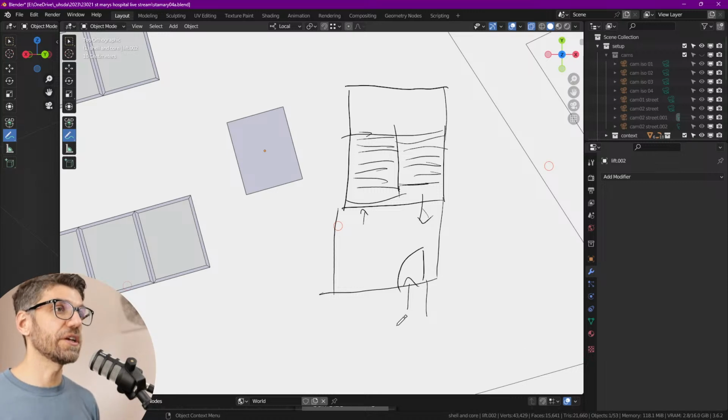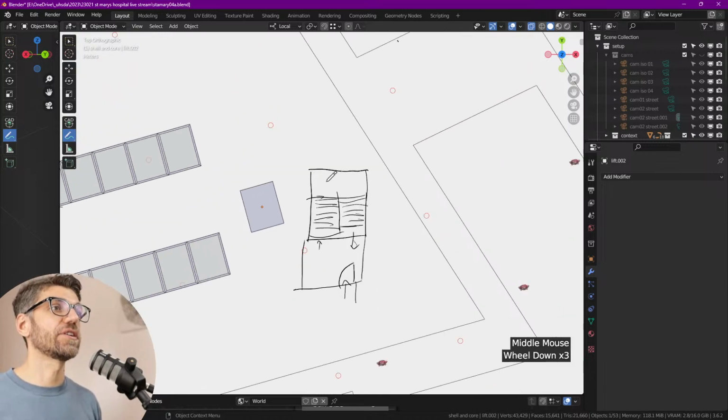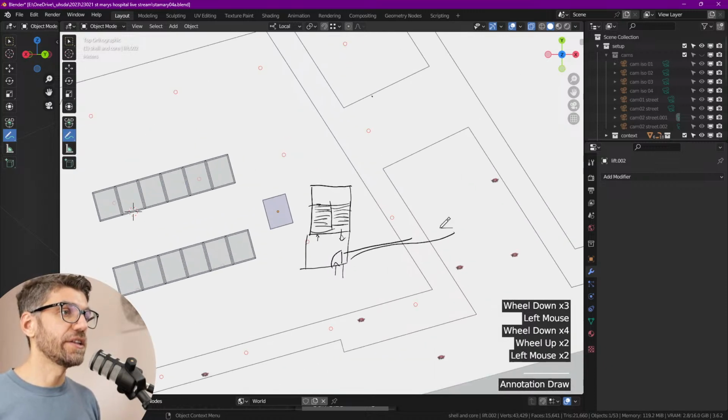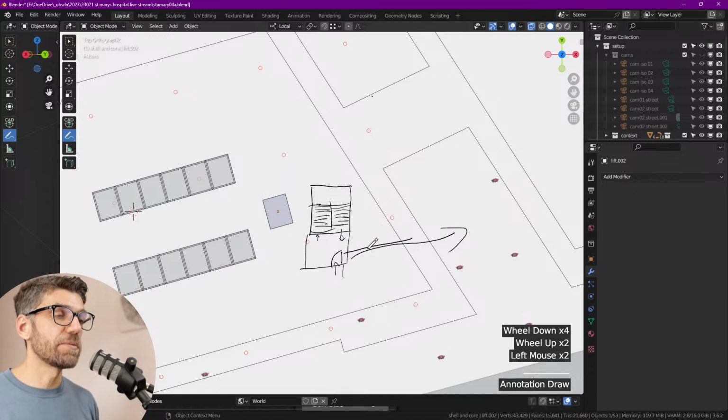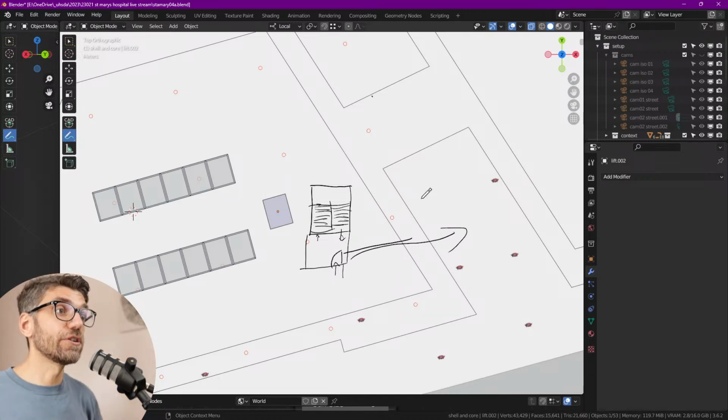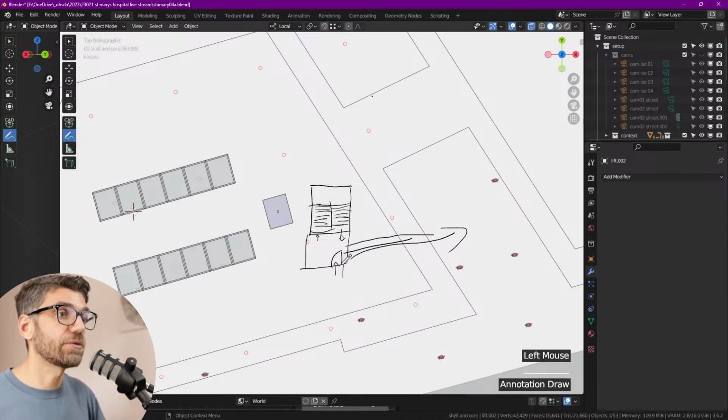An important thing is that it has to have a fire exit way that goes to the outside. In our case, where's the outside? This is the outside. So somehow this needs to come there as quickly as possible. If it doesn't have a door that directly leads to the outside, then it has to have a protected corridor that leads to the outside.